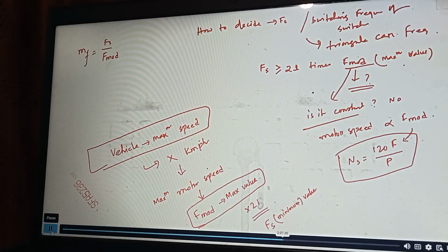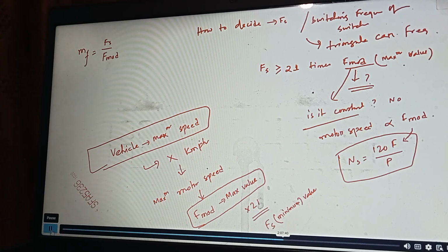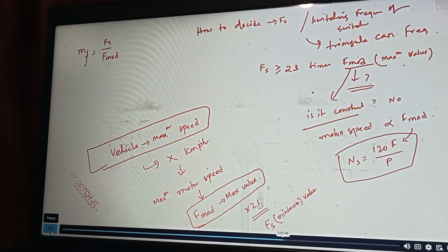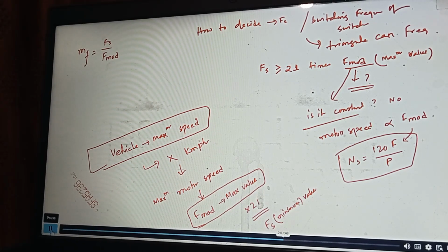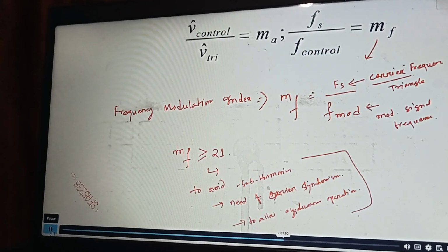Typically, in a motor controller, there is not much benefit of going for a very high switching frequency. I repeat, in a motor controller, there is not much benefit of increasing switching frequency. You can ask why? Because you see in the motor controller output, there is no additional inductor, no additional capacitor we are using.